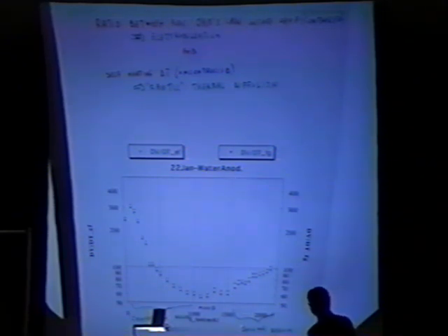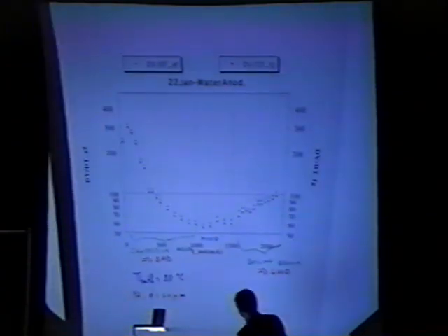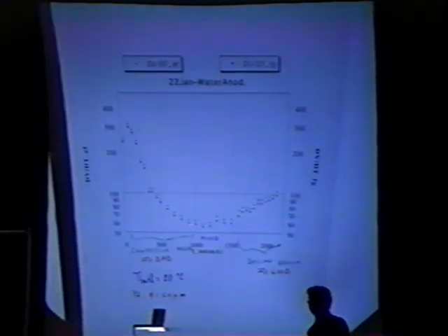But also, if we increase the temperature of the bath from 20 Celsius to 60 or 80, this flat region starts not at 1 ampere, but here at 300 milliampere. So it is better to go to a higher bath temperature. And when this is the loading of the wire, the resistance increases. So with this drop we gain in voltage, so even better. This curve can give us a suggestion on how to optimize the ratio between the voltage applied and temperature.